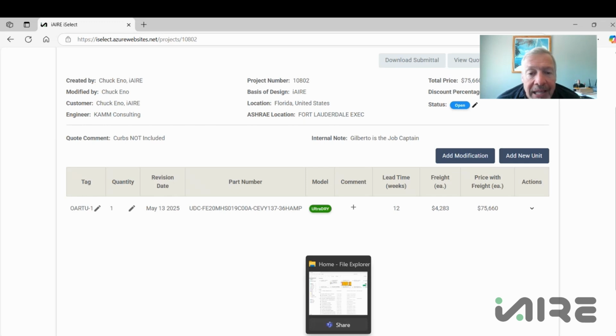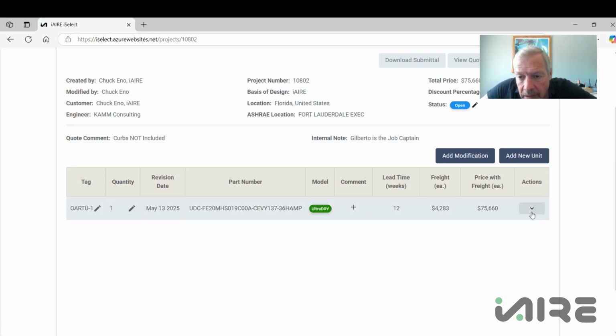The A, the M, and the P. The A is the outside air intake damper. The M and the P are the other options in the unit, which I think, if I remember correctly, we put the blower in there for the outside air intake, and we put the frost protection on the unit.